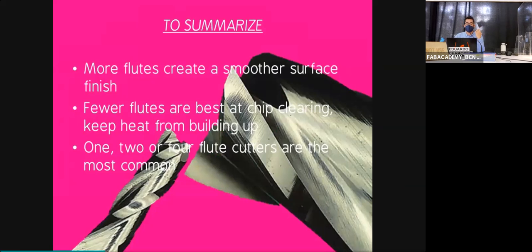More flutes, smoother finish. Fewer flutes are easy to set up because they have fewer problems with heat. 1, 2, or 4 flutes are the most common ones.